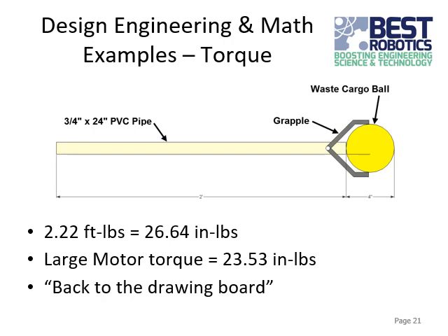And I would add to that, even if the required torque ended up being just below that motor torque, you really want some margin in there too, because if they're basically the same, then it's just going to stall there, and it's not going to lift it very quickly, or it would be really slow. So in this case, it would be back to the drawing board. Can we come up with a different design?